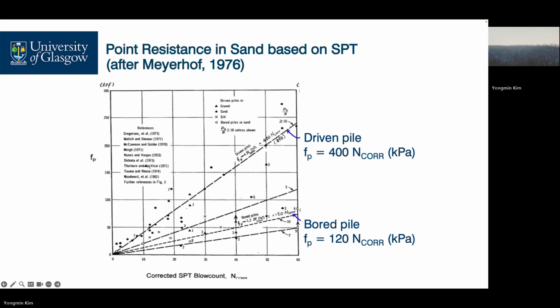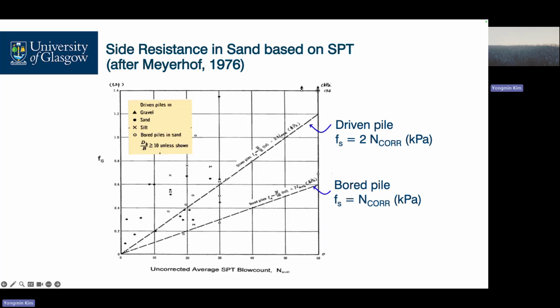We don't know. A lot of uncertainties in terms of the installation, and it strongly depends on the workmanship of site engineers. That's why we draw down the bearing capacity compared to driven. Driven one is just hit, driven to certain layers. It could have good contact between skin and soil, and then the bottom soils. Uncertainties.